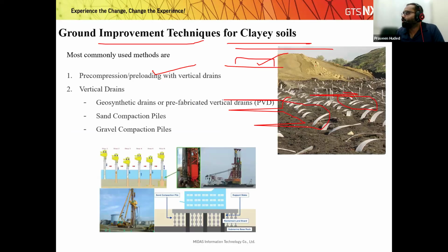Because of the increased surcharge load, there will be an increase in pore pressure, and these drains will act as an escape path for the developed pore pressure. So this is one technique, and another technique is we use sand compaction or gravel compaction piles.